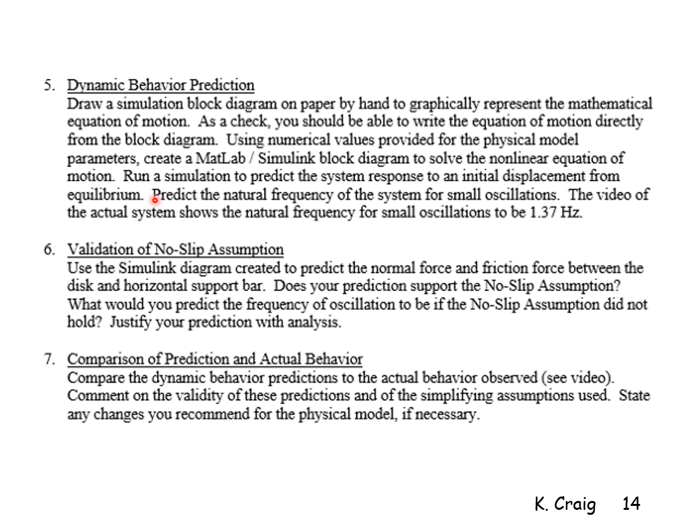So the approximation is that the sine of the angle is approximately equal to the angle, and the cosine of the angle is approximately equal to 1. When the equilibrium condition is at 0 degrees, then we can do hand calculations, and from hand calculations predict approximately what the natural frequency of small oscillations is for the system. The Simulink diagram will do this even for larger angles, larger initial conditions, larger angles of oscillation.